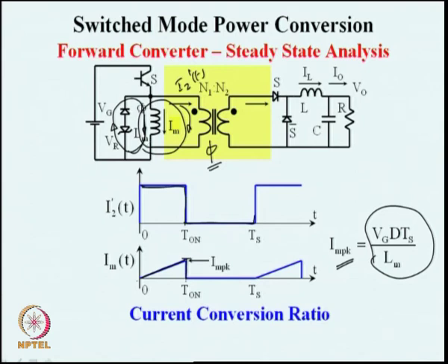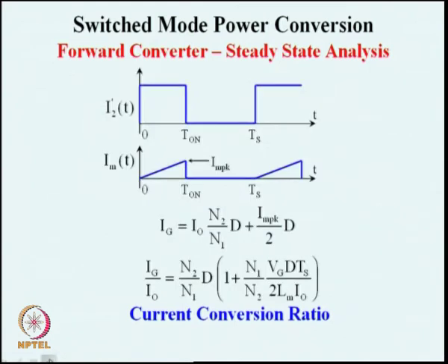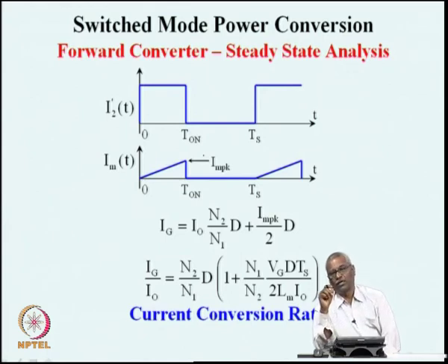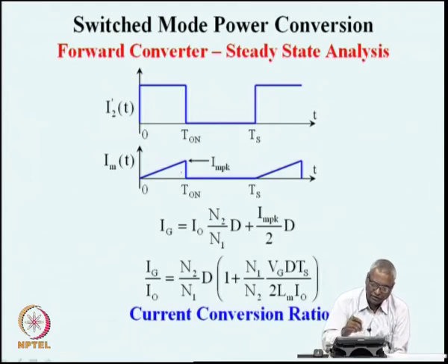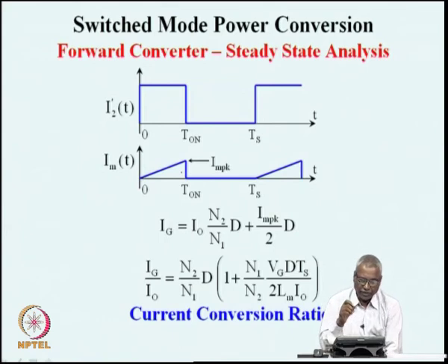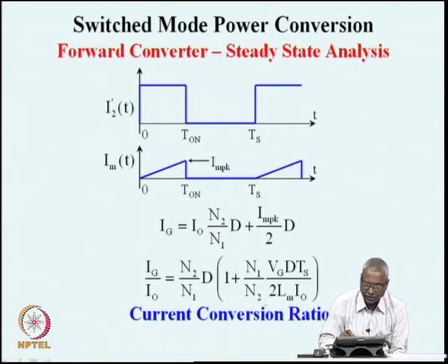In the demagnetizing circuit, the voltage is constant because it is made with a Zener. So, during this demagnetizing interval, the voltage across the transformer remains constant. That will result in the flux being reset gradually.